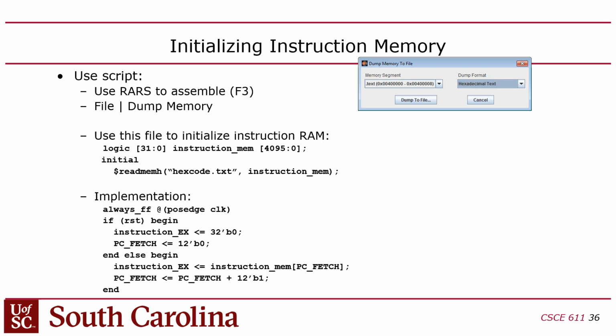Actually, you're using the same project skeleton as last time, Lab 2. There's nothing different. The same one, right? Because you can build this on Lab 2. You just have to disconnect, you have to disengage the switches from the 7-segment decoders.